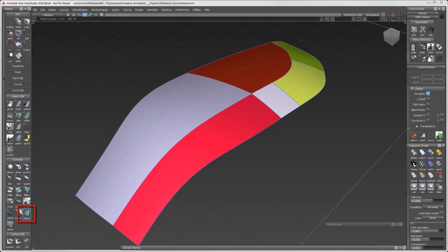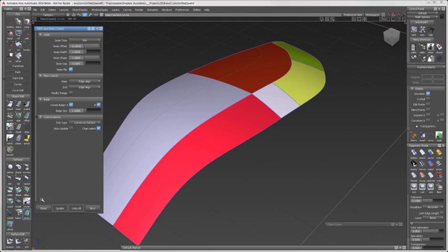The new Stitch and Seam tool rests in the palette under Surfaces. It currently provides three options: Join, which is a seam, French, which is a seam and a straight stitch, and Baseball, which is a seam and an X-like pattern of stitches. You can use either a curve on surface or the edge of a surface for this operation.